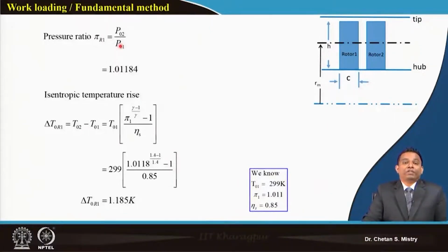One, we have the peripheral speed, and we are looking for the absolute velocity or axial velocity, and we can calculate what will be our relative velocity. Now, in line with that, if it had whirl, you could calculate CW1, but since our entry is axial, my CW1 is 0. But in order to plot my exit velocity triangle, I need to know one parameter or angle. So, we are moving towards that.